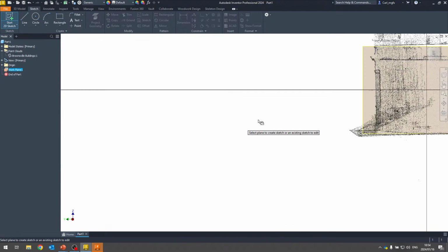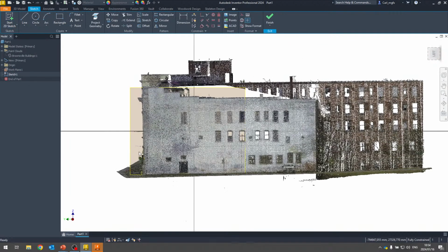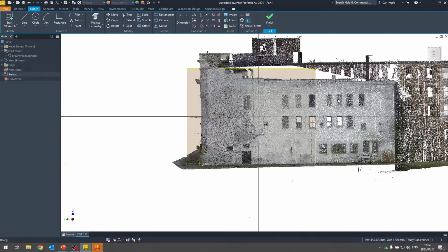Now, once again, if you're doing facility layout, factory planning, then you would be looking in a plan view and setting your machinery where it needs to be. The scan would be of the internals of the building. You'd also be able to then see, does your machinery clash with any rafters, any columns, are there any services within the building like water, electricity, pneumatics, ducting that your machinery is clashing with.